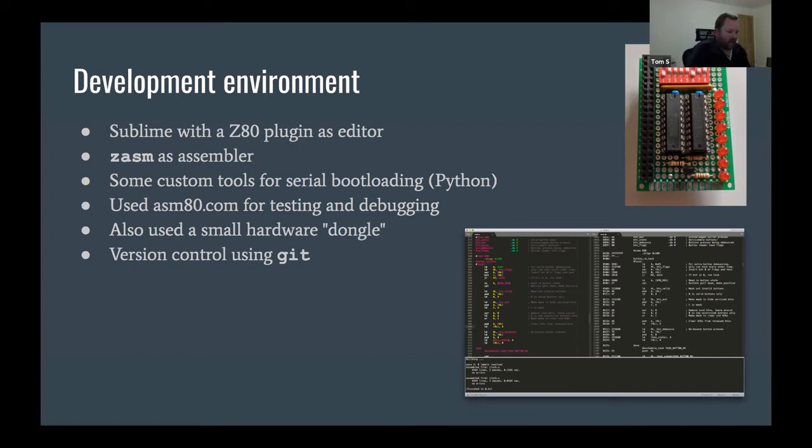I guess the Python serial module I was using doesn't really know how to control it, or there's something wrong with my cable, but I couldn't get that working. So that was a bit of a shame, but it wasn't too hard to just reach around and push the little reset button and then just run Control B and then upload the software.